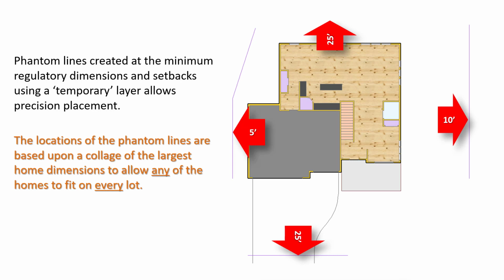Most of the time, when we're working on these developments, if the ordinance doesn't allow for the porch to extend into the front setback, we ask for the porch to be allowed into that front setback. That way, the builder is not being punished for having a porch, because if you don't do that, adding a porch is going to impede on the square footage of the usable part of the home. This way, the home doesn't have to sacrifice usable square footage for a front porch. Even if it's a PUD, it's a minor ask, and almost every city has approved that ask.